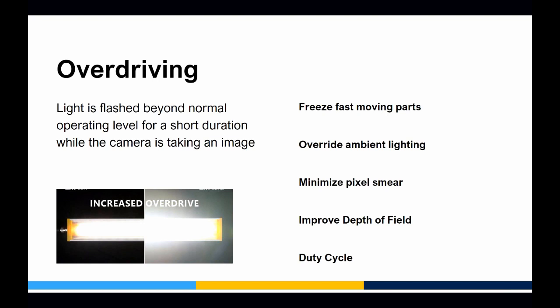So these limits are going to be based off of the controllers and the lights. So Gardasoft will have a table of, if you're using it from this intensity, 200 to 300%, respect this duty cycle, 300 to 400%, respect this duty cycle. And CCS, as I mentioned before, will also have overdrive ratings that we will provide when asked. So it's just important that you're making sure you're giving your LED enough time to rest between flashes when you're talking